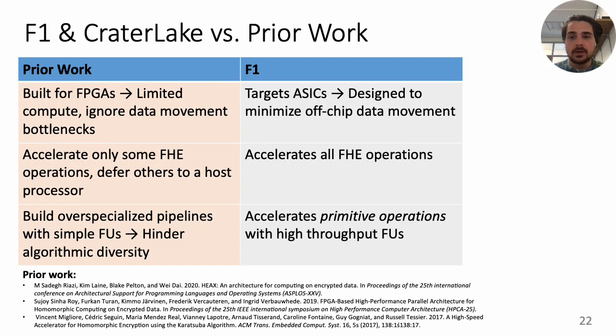Jumping into F1, here are the principal differences between it and prior work on FHE accelerators. We target ASICs instead of FPGAs, forcing us to reckon with larger data movement problems. We accelerate entire FHE programs instead of only specific kernels. Finally, we accelerate primitive operations instead of building over-specialized pipelines.